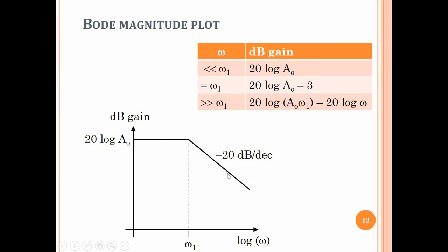So depending on the frequency, the output magnitude of these voltages applied at the input will be very small. For that reason, this omega 1 is called the cutoff frequency, to say that for frequencies above omega 1, any signal that is applied at the input will be attenuated, or cut off, quote unquote. As you may know, this circuit is called a low pass filter because it allows low frequencies to pass through, and it does not allow higher frequencies to pass through.